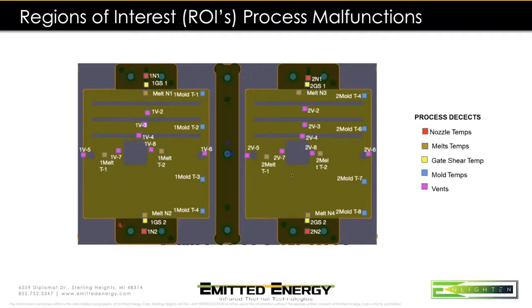That dog bone that's in the middle there, there's also 2 on the outside. Those are standoff pads that we can add a couple thou for venting and show you when the venting is starting to clog. If we put a thou in, how it gets rid of and takes care of the closed off vent problem. There's many things that we can show you with those nozzle temps as we go up and down and delay them to simulate any kind of problems that you would have on your process as well.